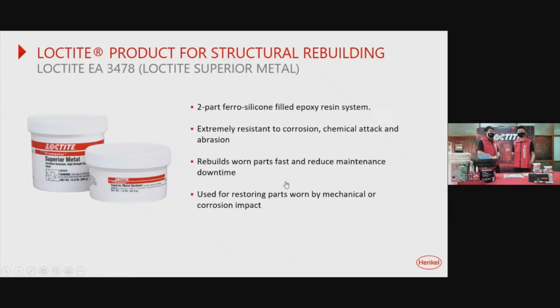One of the key characteristics of this product is that it is extremely resistant to corrosion, chemical attack, and fine solid abrasion. We are able to rebuild lost metal parts using this Super Metal with a very fast curing time. Normally we can use this for shaft repair, pump housing repair, or impeller repair, this kind of thing.